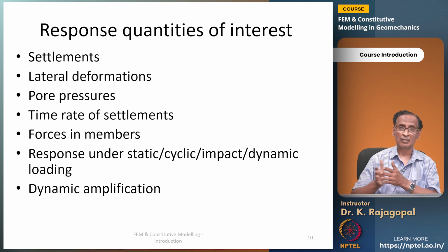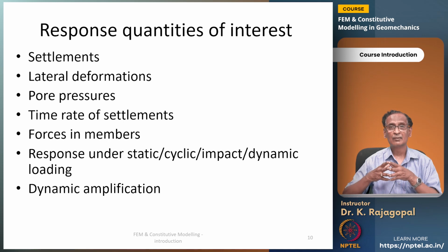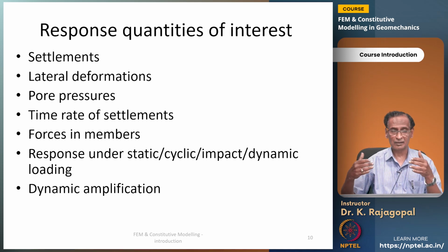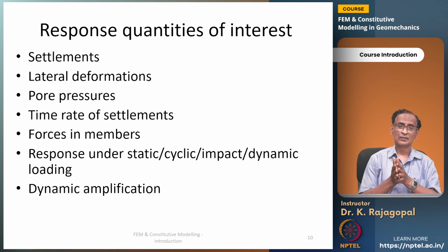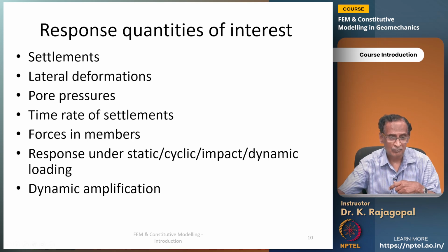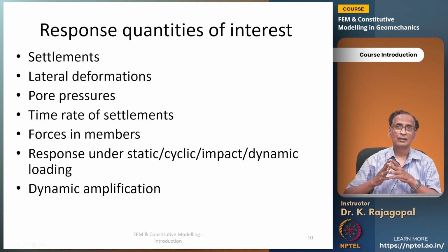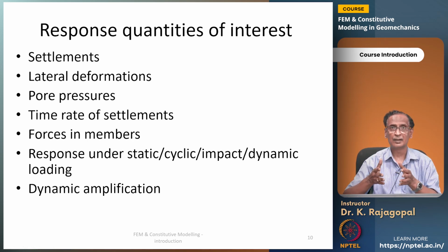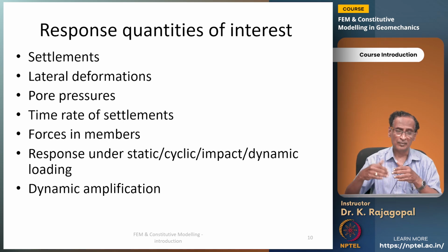And if you are doing any construction on soil with water, what are the pore pressures. And then if you are dealing with soft clay, what is the consolidation, what is the time rate of settlement, because this could govern our designs. And if you are not able to get rid of your settlements in a short time, you might want to go in for some ground improvement.